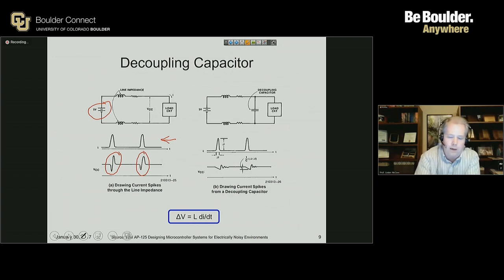The equation that we're taught in our theory classes that relates the size of those voltage excursions to the circuitry is this equation at the bottom of the screen, where we know V equals L dI/dt. What we're talking about here is a delta V, or the size of the variance that you have on your VCC lines. First question is why is delta V important to us? Why does it matter how large of a noise you have on your VCC lines? Can anybody comment on that?